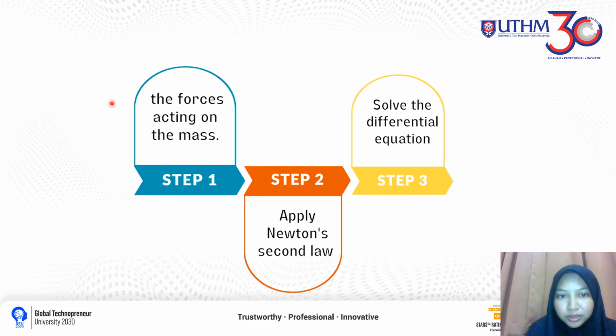Now we move to the method of modeling the spring mass system, which has 3 steps here. We can see step 1, the force acting on the mass. Step 2, apply Newton's second law. And step 3, solve the differential equation.